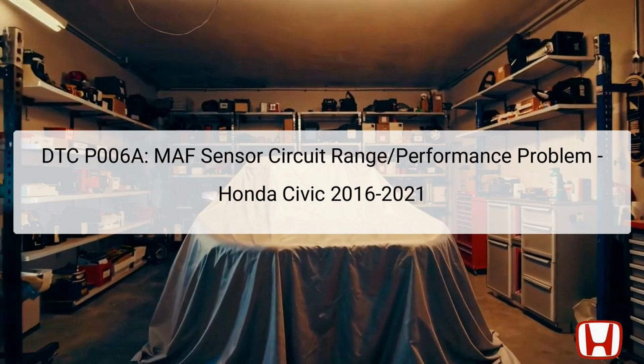The DTC (Diagnostic Trouble Code) P006A indicates a MAF (mass airflow) sensor circuit range or performance problem, specifically in Honda Civic models from 2016 to 2021. The MAF sensor is crucial as it measures the amount of air entering the engine, allowing the engine control unit to optimize fuel delivery for efficient combustion.